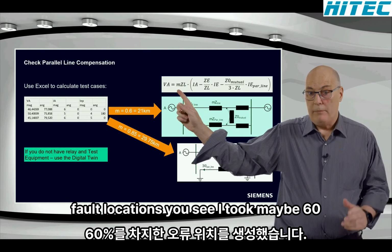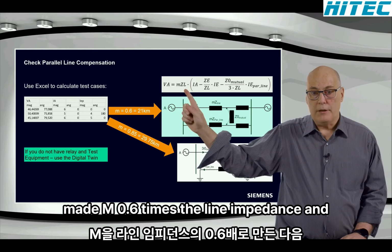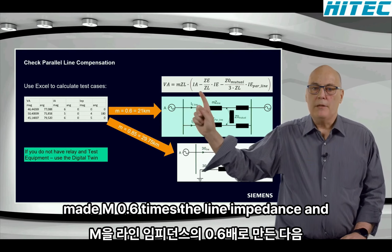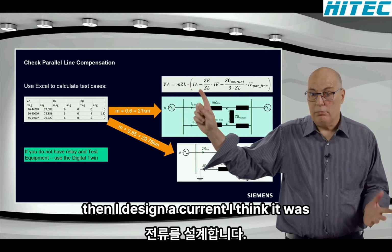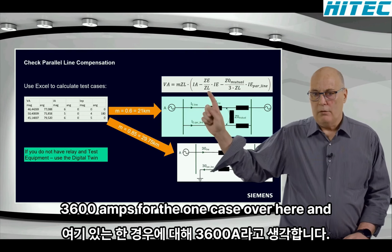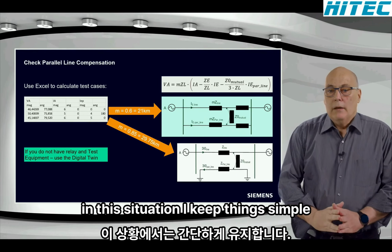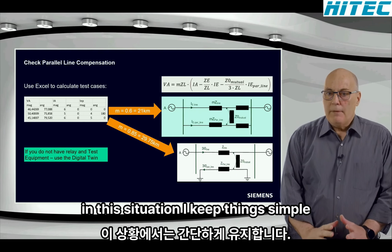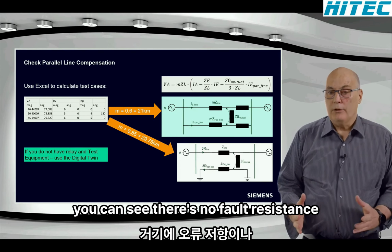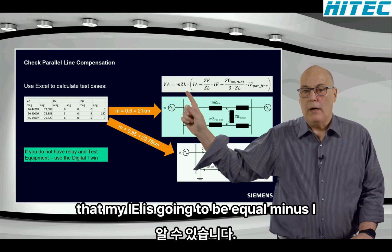You see I took maybe 60%. I took two faults at 60%. I made M 0.6 times the line impedance, and then I defined a current. I think it was 3,600 amps for the one case over here, and then the IE would be automatic. So in this situation, I keep things simple. You can see there's no fault resistance or anything in there, and then I assume that my IE is going to be equal minus IA.